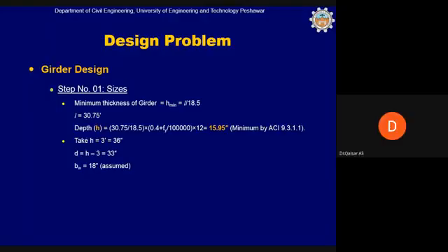And you know that delta, which is the deflection at the midspan, will keep on increasing with the increase in load as well, not only with the length. It is obvious that delta will increase with the increase in length, but it will also increase with the increase in load, W. But in order to simplify the equation, the ACI code has omitted the load part and only included the length part. But there is a disadvantage to this simple equation, and the disadvantage is that it does not contain the load part.